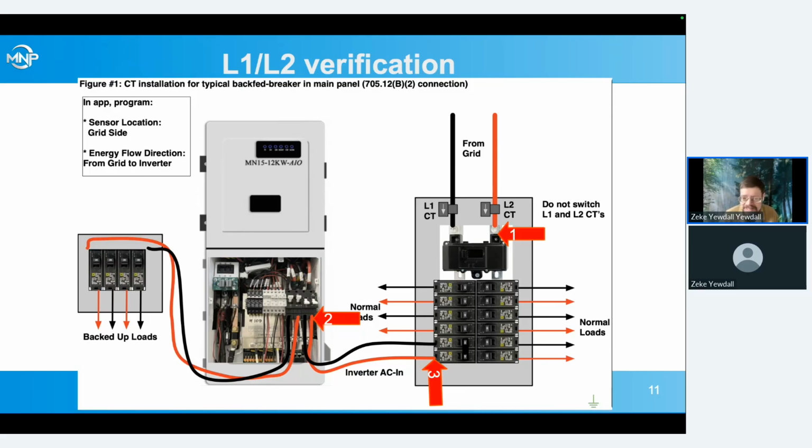Often where that happens is if you can't really see that bus bar behind all of these breakers really well, you may not be able to tell, is phase two the lower terminal or the upper terminal on that breaker. It might be different depending on the exact bus bar layout. Also, we have seen main breakers here where it actually crosses the two phases going through the breaker.